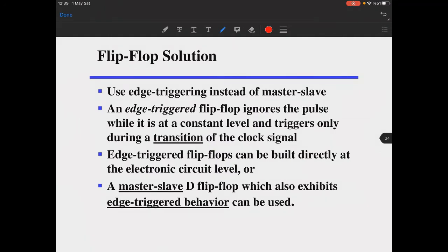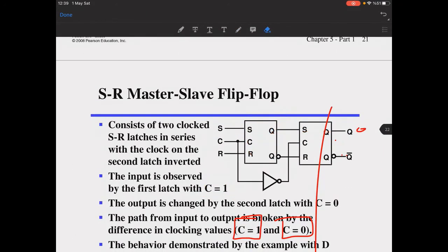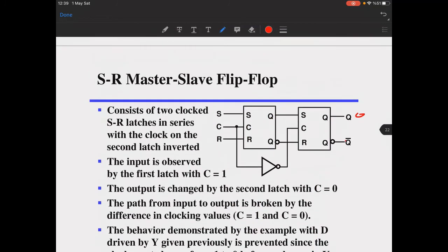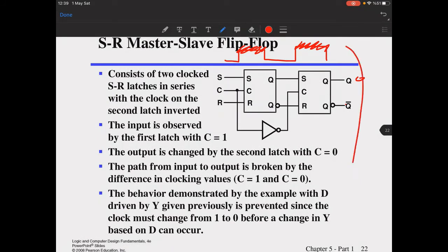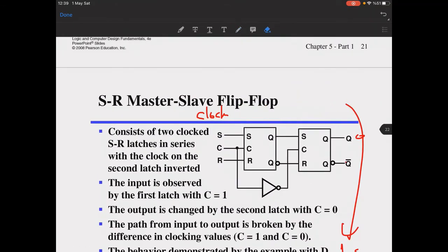Instead of making the transitions strictly at the clock signal here, where the transfers are allowed during this time, which, as you see, causes the ones catching problem, provided that this is your clock signal, you try to build a structure where the updates happen only on positive edges, for example, of this signal.